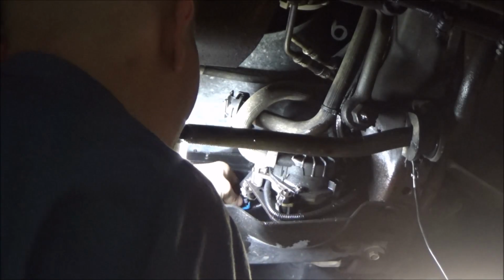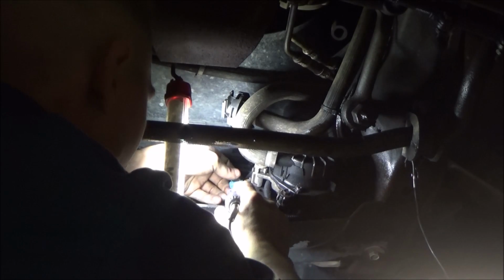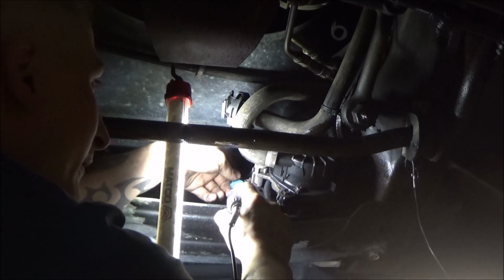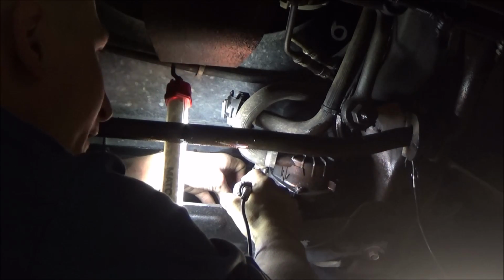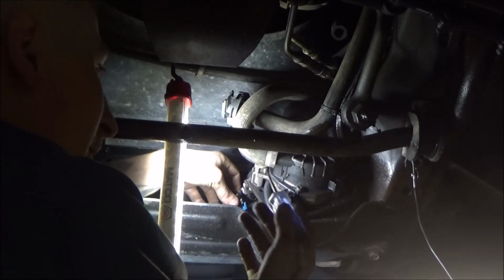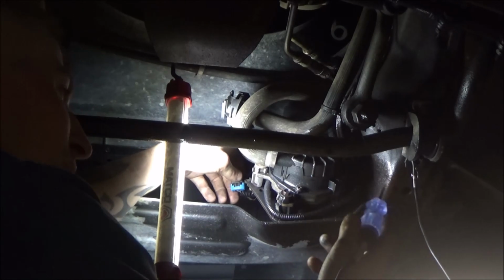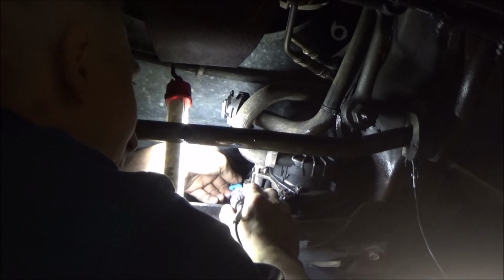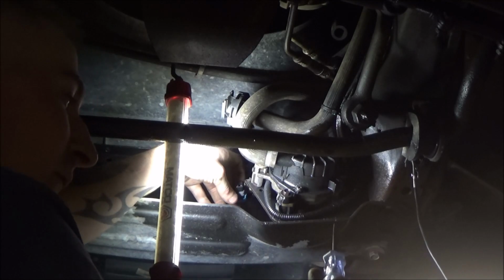So what I'm going to do to verify that is put a T-pin through the backside of one of these solenoid connector wires, and then we're going to front probe the other one, and we're going to verify a good ground that way. We're basically just going to use this test light to supplement the load in this circuit and confirm that our circuit integrity is okay. You know, we could also switch our test light to battery positive and do this. Using a test light, we cannot just back probe the ground wire and attempt to make sure that we have a good ground that way, because really all we're going to do is energize the solenoid.